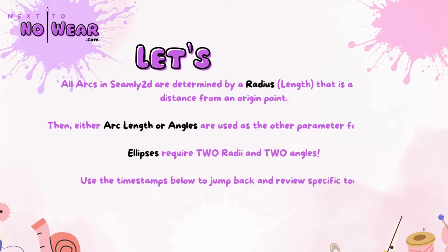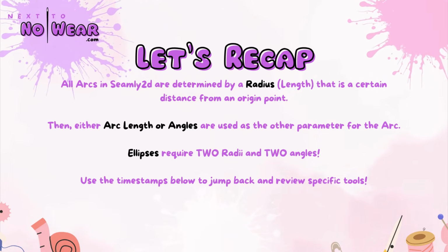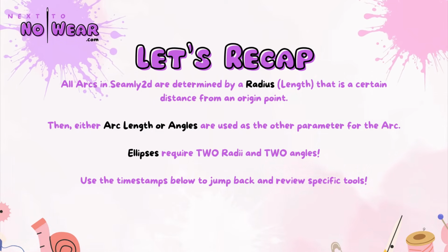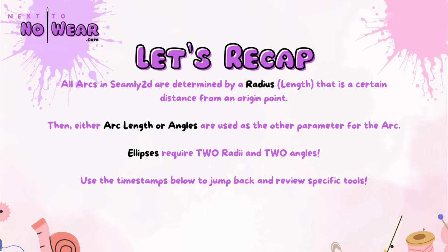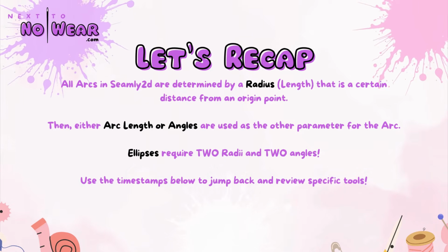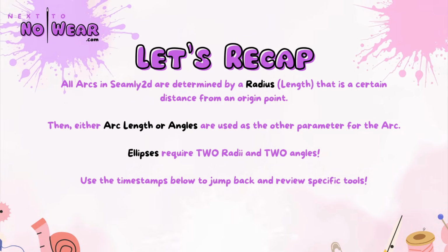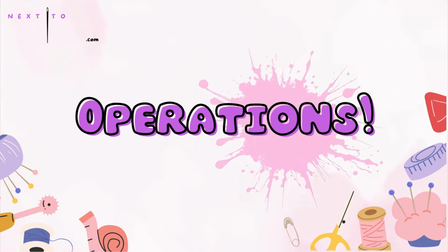Let's recap part 4. All arcs in Seamly2D are determined by a radius that is a certain distance from an origin point. Then either arc length or angles are used as the other parameter for the arc. Ellipses require 2 radii and 2 angles. And as always, use the timestamps below to jump back and review specific tools. Our 5th topic will be operations you can perform on the objects you've already created.